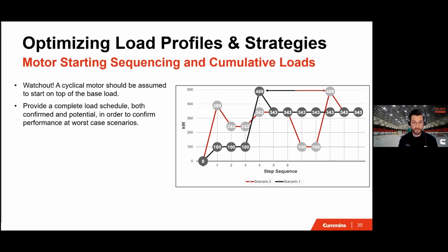So as we take a step back on that exercise on load sequencing a motor among other loads, one key caveat is that those motors serving life safety loads, such as fire pumps, should be sized and sequenced as if it was not started ahead of other loads. We basically need to think pessimistically or conservatively to ensure there is plenty of capacity for starting such loads, even when it is out of the most ideal load sequencing order.